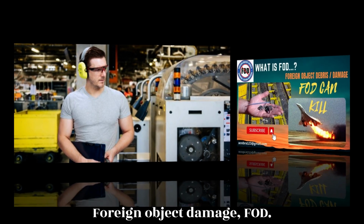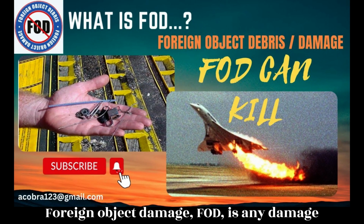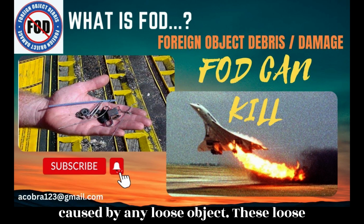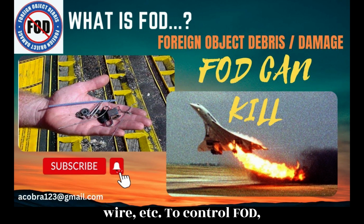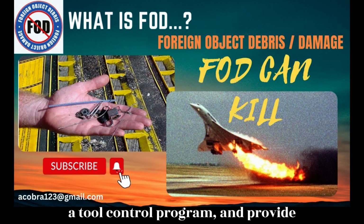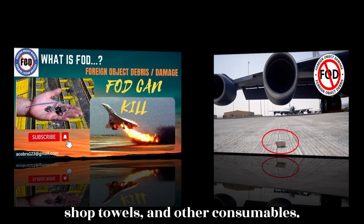Foreign object damage, FOD. Foreign object damage, FOD, is any damage to aircraft, personnel, or equipment caused by any loose object. These loose objects can be anything, such as broken runway concrete, shop towels, safety wire, etc. To control FOD, keep ramp and operation areas clean, have a tool control program, and provide convenient receptacles for used hardware, shop towels, and other consumables.